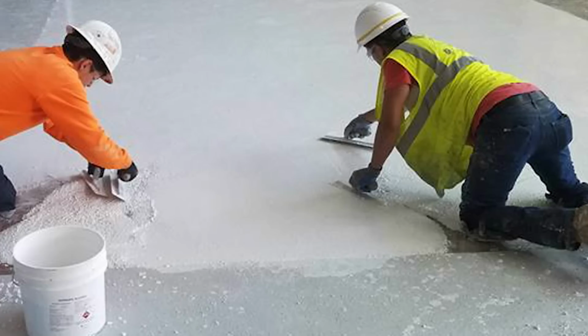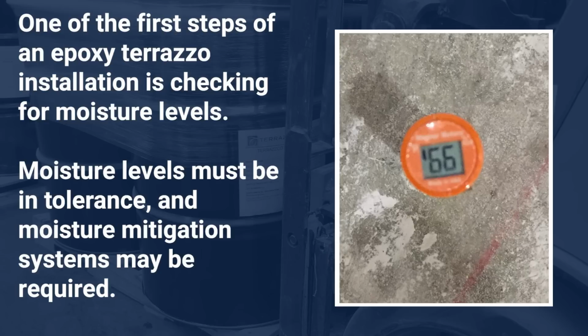Installing terrazzo is an art in itself. The craft requires various skills that have been passed down from generations. When thinking about installing terrazzo, it is best recommended that you hire a professional contractor rather than installing the material yourself. So when installers first enter a construction site, it is important for them to perform moisture vapor transmission tests on all slabs receiving epoxy terrazzo.